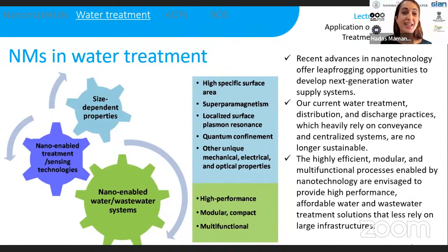So not only test with, I don't know, DI water or water with some type of buffer. It should work with water that has other constituents inside, and also particles, maybe colloids. Because if before the sorption technology we don't have a UF filter, then maybe we'll have colloids in the water, and that will also impact our technology. So in technology design, as environmental engineers, it's very important for us to emphasize all these factors, okay?